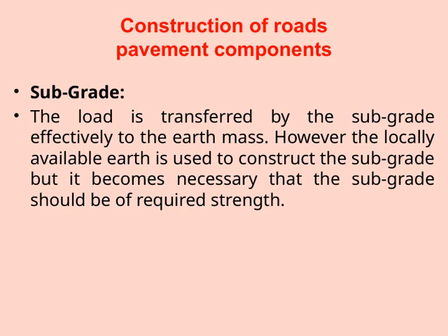Now, let's talk about the subgrade. The load from the pavement is transferred effectively by the subgrade to the earth beneath. It's important to note that often, we use the locally available earth to construct the subgrade. However, this earth must have the required strength to support the loads and prevent future issues.